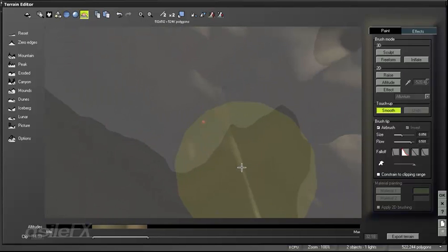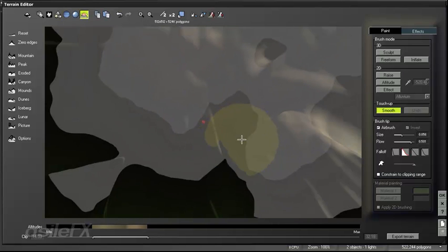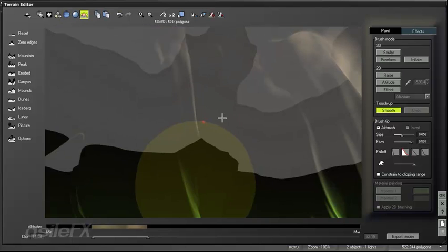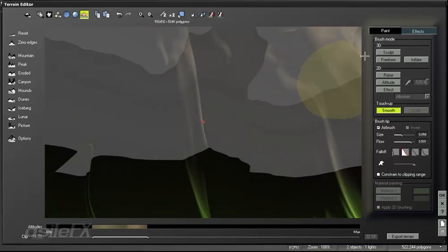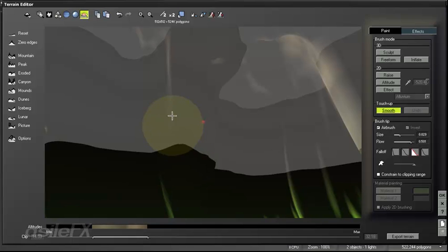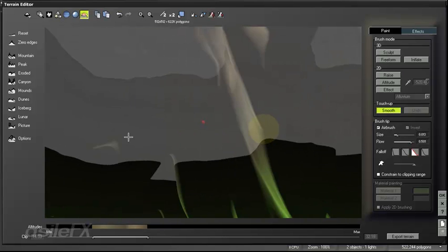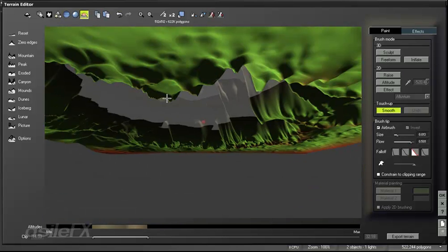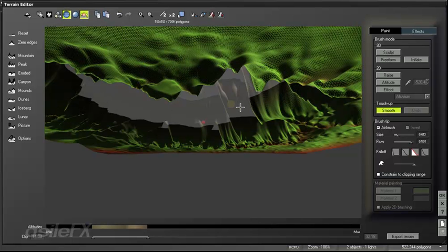I see a very obvious crease here. So what I might need to do to get rid of that is first inflate it and then smooth it out, and then adjust the level of detail, the size of the brush, to be able to get to that lower geometry level and fix anything else that might cause a problem. Now I did just divide the geometry,